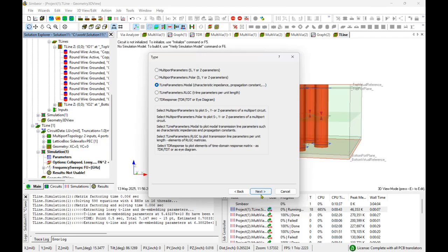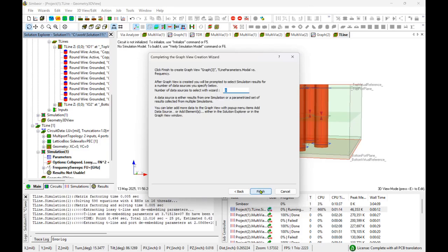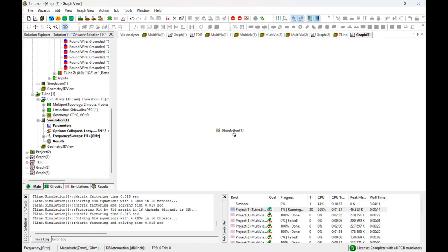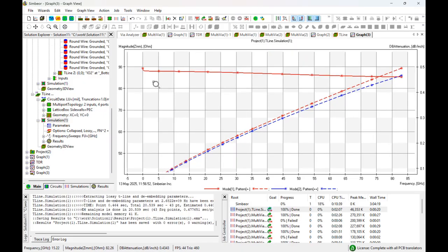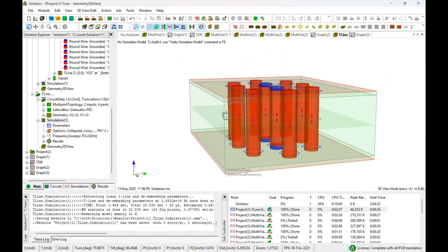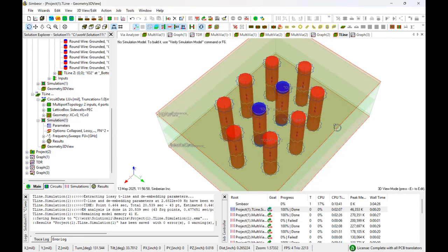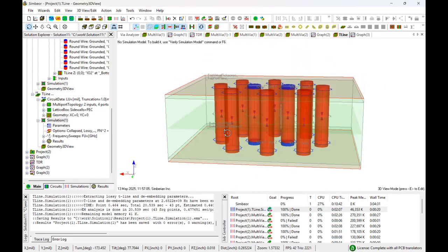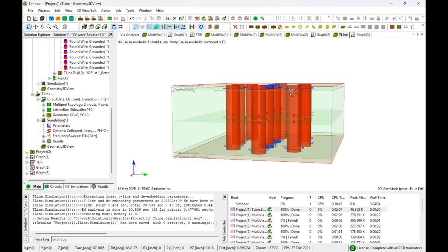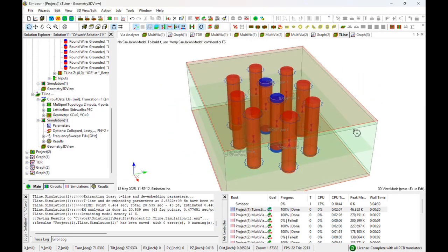And plot the results as transmission line. So transmission line model, and mixed mode impedance. Okay. Bring this here. And you can see this is about an 87 ohm transmission line. This structure here. So if you need it under BGA, you'll need 12 of those. You can position them more like under BGA. And this thing is a basic element of any stack-up via, again, for the differential case.